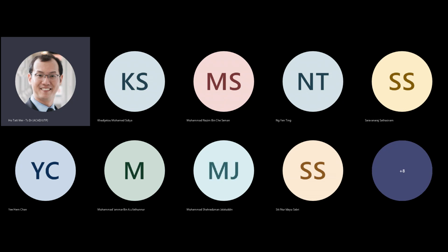And the key finding in the short channel domain is really that the current is no longer dependent on the square of VGS. It is approximately dependent on VGS to the power alpha, where alpha is quite close to 1. So the current now is almost linear with VGS, with the drive voltage here. Okay, so there is a corresponding weakening of the transistor drive strength as we scale, as we go down to smaller and smaller transistors to build our devices. So that's the important point there.